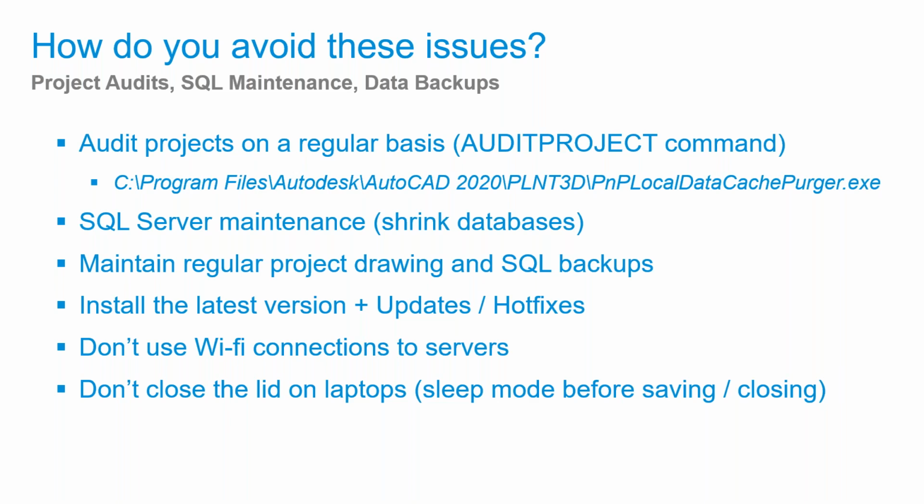And really what you want to do is go ahead and audit that project. And then if you want to clear your local cache afterwards, that's just kind of general housekeeping for plant projects. It never clears out that local cache that it's generating as you're working. So you may have that cache get what we call stale or out of date. So it's always good to just flush that out every once in a while.